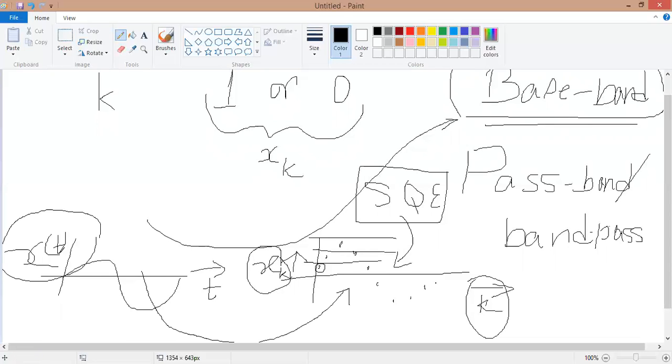On the other hand, what is the purpose of a carrier? A carrier is required only when I want to send the information over the longest path. If I want to send the information over the longest path, I need an antenna, and the antenna height may be reduced using some modulation technique. Modulation here is possible using some carrier which can carry the message. Now, this is related to your passband modulation or bandpass modulation. In case of baseband modulation, DPCM, PCM, DM, ADM are baseband modulation. On the other hand, bandpass modulation or passband modulation are ASK, PSK, etc.